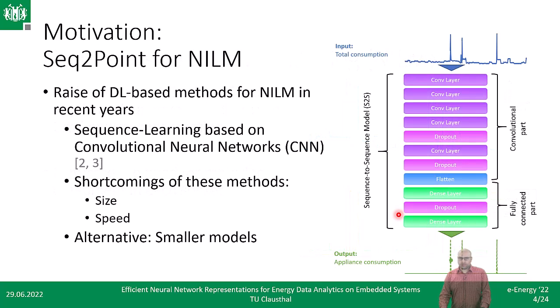Modern solutions for the NILM problem are actually based on deep learning and neural networks, especially sequence-based neural networks. They disaggregate a window of samples of the total energy consumption into the consumption of one appliance, on which the neural network has been trained.